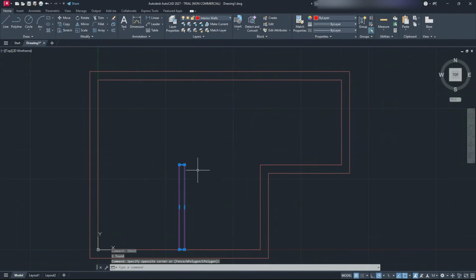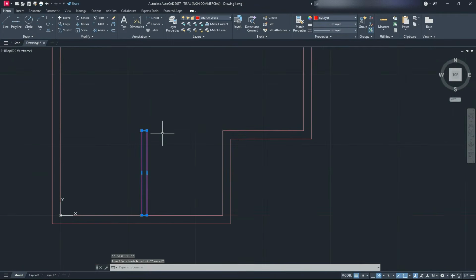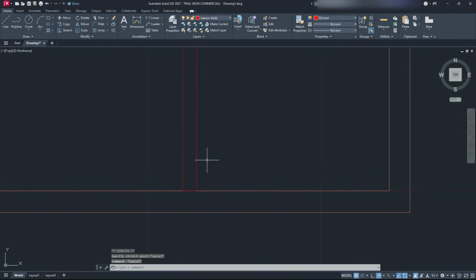Another way we can do it is you can just take this, zoom out a little bit more, and I'll just pull it out again. We just select it, grab the same tool from before, and then we can just highlight this, and you can see that green dotted line is coming, and we can drop it like that. Or another way we can do it is we can just drop it by what we need. If we do the math between the distances, we can just drop it by that. To do that, you just grab and then pull down, and you're going to see it says polar, and that distance that you see beside that is the difference between where it is now and what it's going to be. So just keep that in mind, and then we'll have our interior wall.